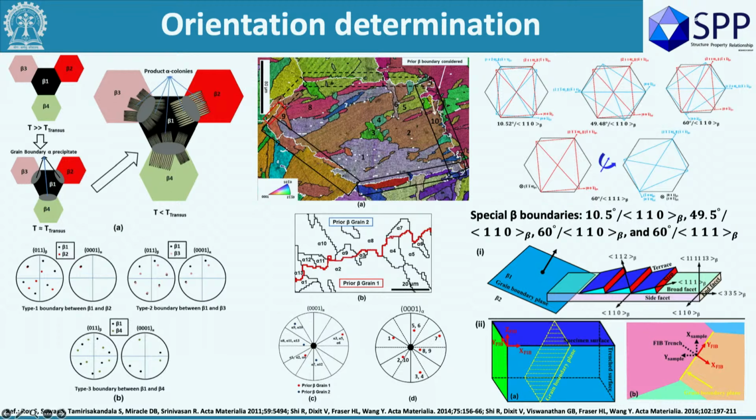Complex business. And the funny part is, the mechanism that I told you till now is not always valid. There are other mechanisms as well. There are other conditions as well. Under those conditions, the beta orientation or misorientation will not be the deciding factor. The deciding factor will be the relative misorientation between the beta grain boundary plane and the habit plane. That also happens. Then the entire story that I told you proves wrong.